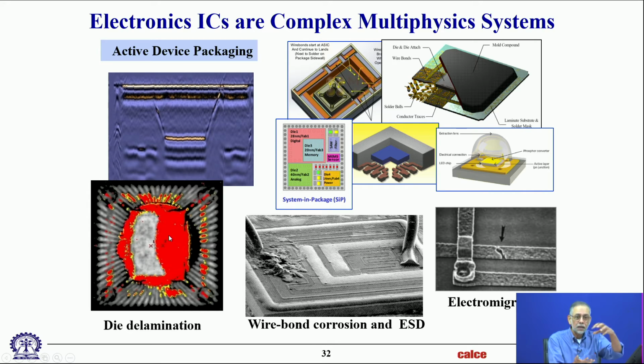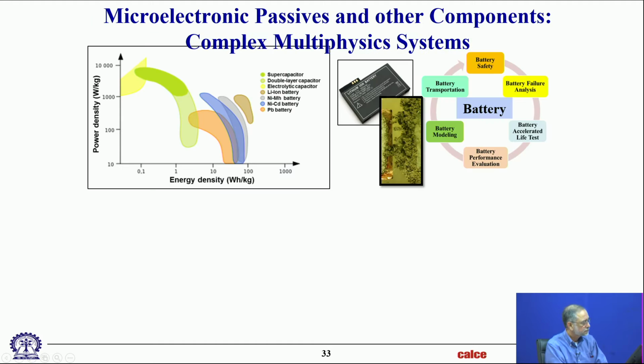The red regions are in an acoustic scan. You're seeing the reflected signal showing you delaminations. So eventually, you get delaminations like that. Moisture then accumulates in those delaminated regions, accelerates the corrosion. So all of these feed on each other, they're chain events. Okay. So there's just 3 examples of the kinds of failures we see within packaged ICs. I'll go through a more exhaustive list this afternoon.